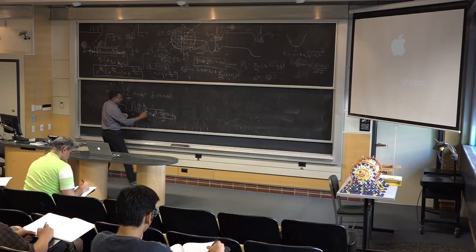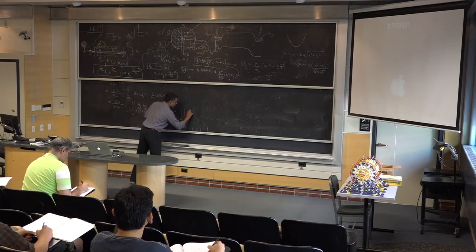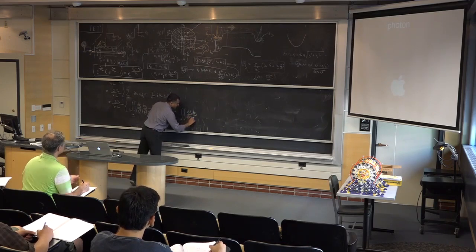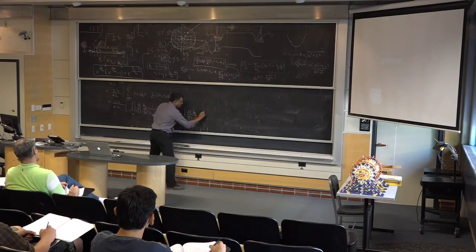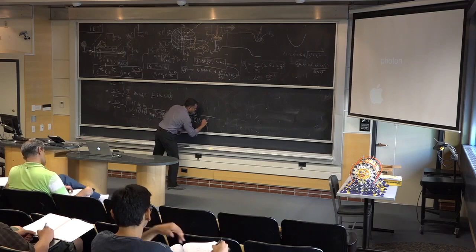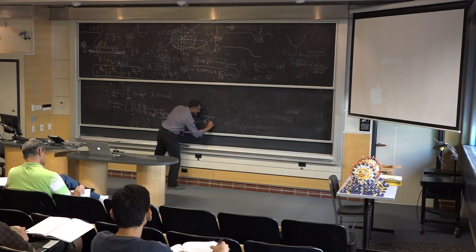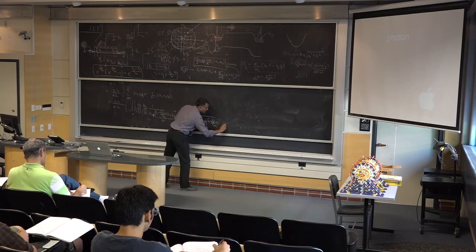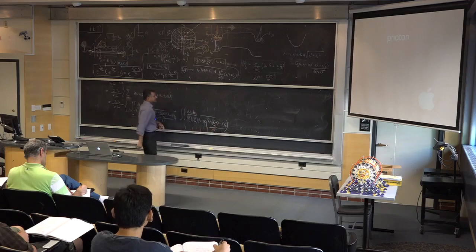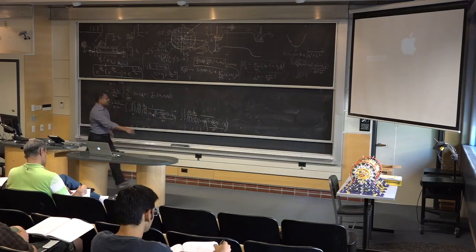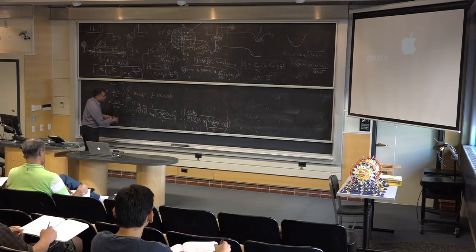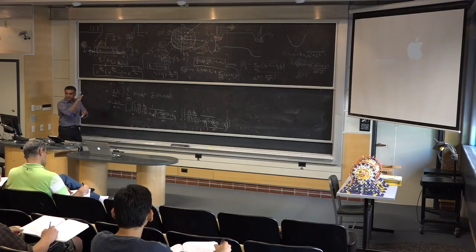And now, there's another term exactly like that. Well, since we had it, let's just write that down. It's just going to look a little forbidding, but really it's the same deal. 2 pi by L, 2 pi by W, exponential of conduction band edge plus the same deal, kx squared plus ky squared, effective mass of conduction band minus the Fermi level of the drain now. Okay, so that's over kT. That's your full-blown expression. And then the thing is, you notice right away a few things. Is this clear or any questions? I mean, essentially we just split it into 2. Okay?